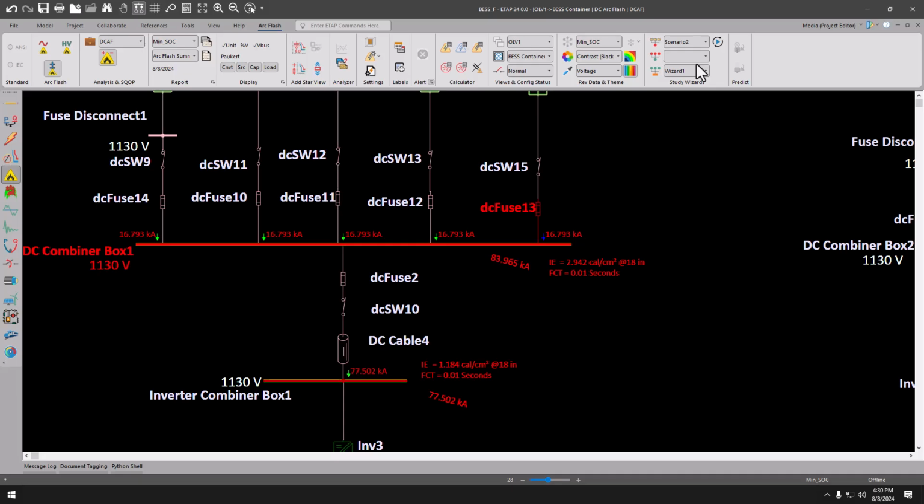Now, of course, depending on the different constraints that you may have, the process of doing this may change a little bit, but overall, we can see the benefit of how these reference curves can easily be used as a visual inspection during the protection and coordination phase as we pick protective devices for our design or as we pick the adjustable settings, for example, for breakers, to make sure that as we consider protection and coordination criteria, we're also in parallel able to select settings that help limit the amount of incident energy exposure at each of these faulted locations to a manageable limit.